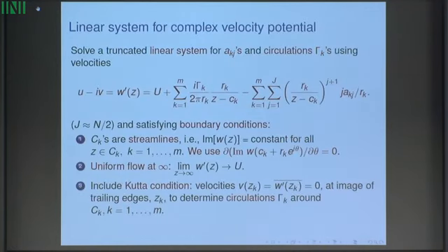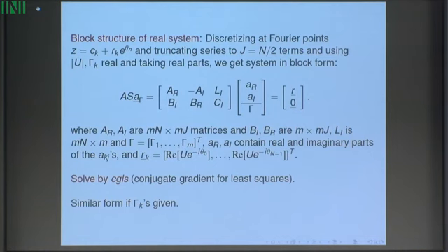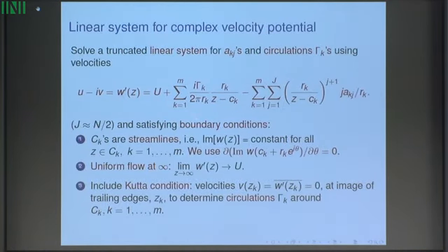All right, now I'm not going to tell you all the details about the linear systems. As I say, I keep pressing the wrong button here. We need boundary conditions for the potential flow, and those are that the circles should be streamlines. In other words, the imaginary part should be constant. What I use is that the derivative with respect to theta should be 0, and we set up a linear system from that. We want the flow to go to u at infinity,